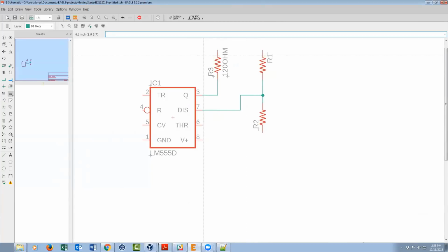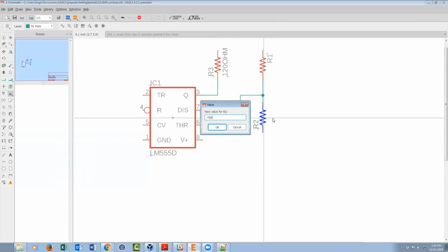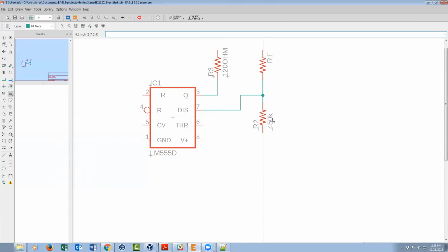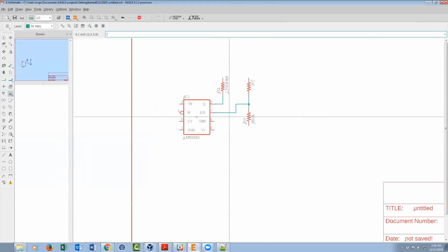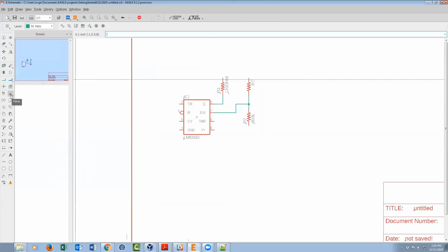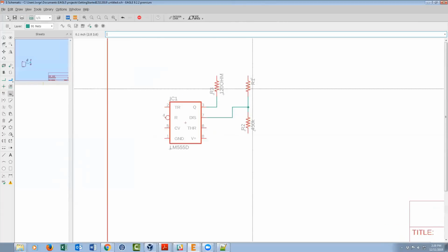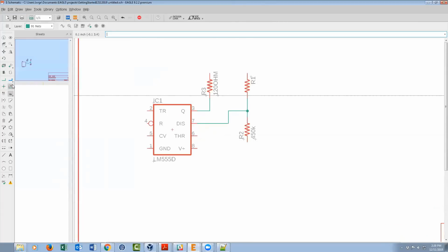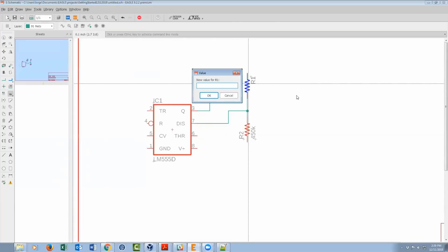Okay, and I apparently have my caps lock on, so sorry about that. Okay, 450K, etc. Now, a couple of things we can do. You'll notice that the command stays active, and that's key to Eagle. Okay, you select what you want to do first, and then the components you want to do it on. So again, I'm still on value. I can assign more values here.